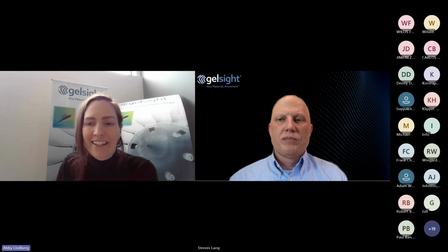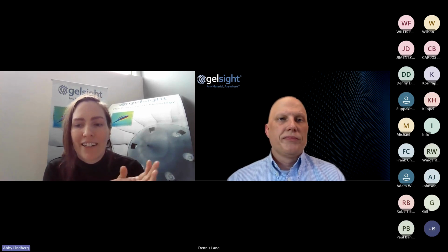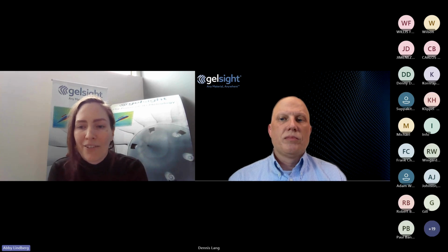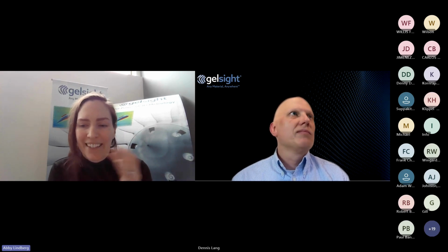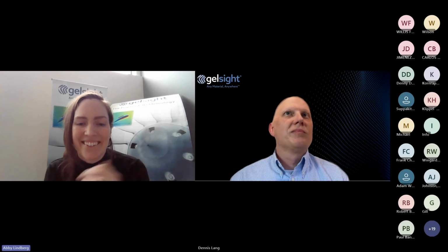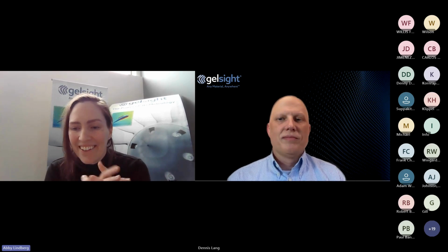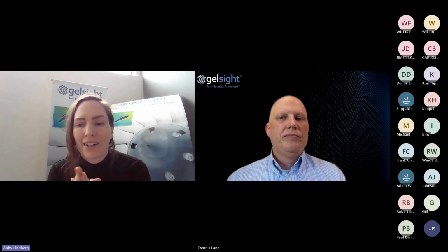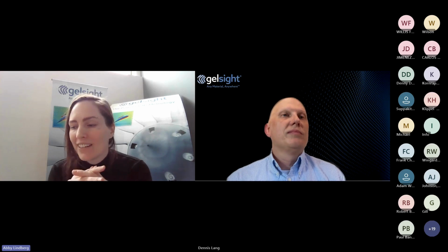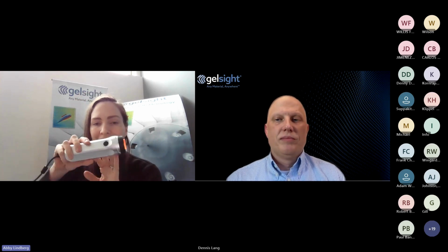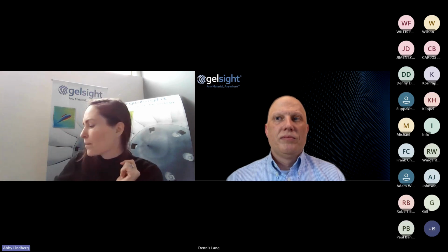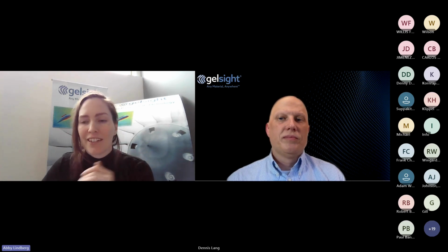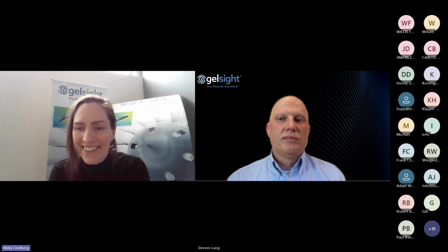We have another question that said, is GelSight capable of measuring and quantifying surface roughness, and what range of roughness can it measure? And also thank you to Frank, who's been answering these questions throughout. But I'll add something to this one too. So the GelSight Max system will go down to 0.2 micron Ra and up, and the Series 2 system that I'm using here today is about 2 micron Ra and up. So that's 80 micro inch for anyone interested in those as the units.